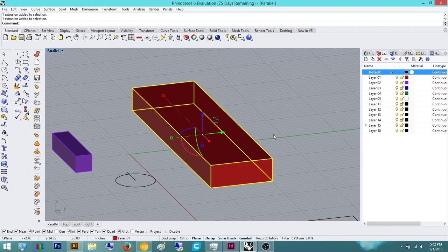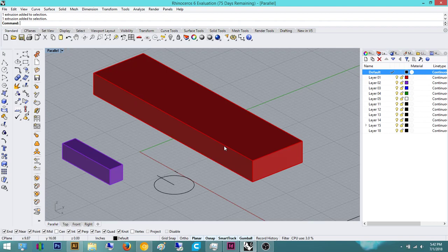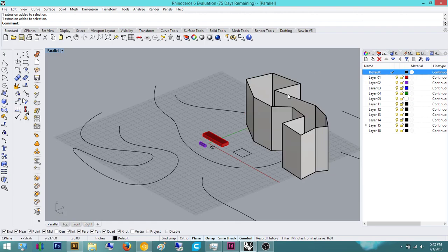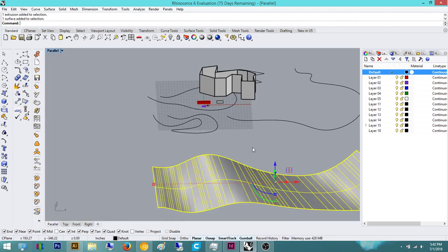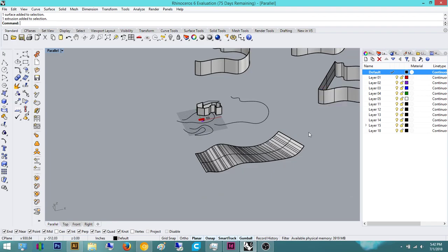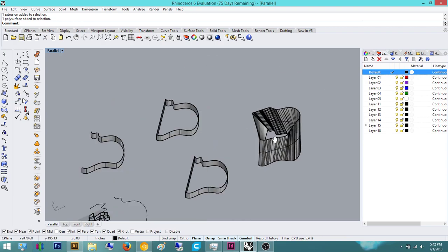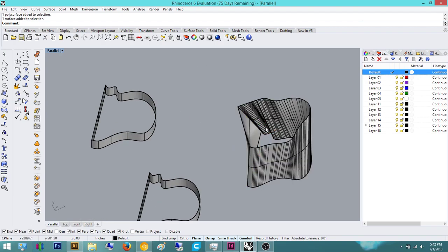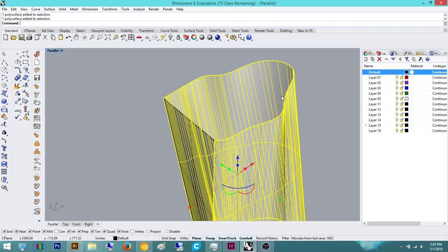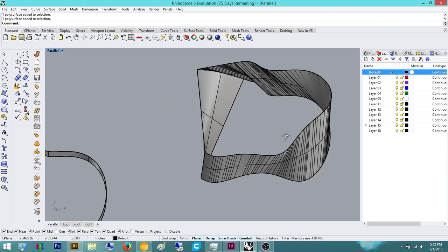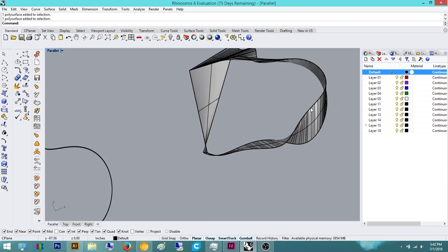But an extrusion is still a polysurface. This is also still considered, I think that's an extrusion. This is a surface. This is also an extrusion as well, and this is a polysurface. So this is still a polysurface, as you can see, but the difference between this type of polysurface, so this is a quote-unquote bad polysurface, because as you can see, there's a giant opening at the bottom. You can see right here this gray. That means it's still an open solid, a quote-unquote open solid.